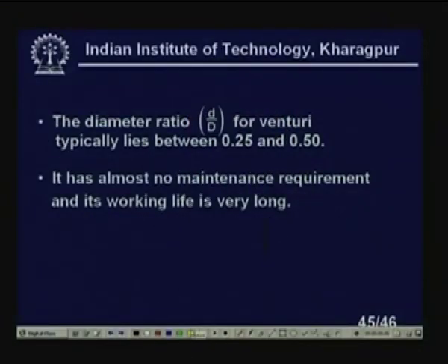use, that means if you look at the orifice, if you take it like this, and if this edge loses its sharpness, instead of like this it gets rounded like this, right, then the entire calibration will go wrong. This type of situation does not arise in the case of the venturi meter. That is the great advantage of the venturi meter.